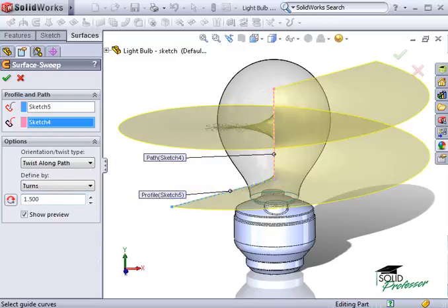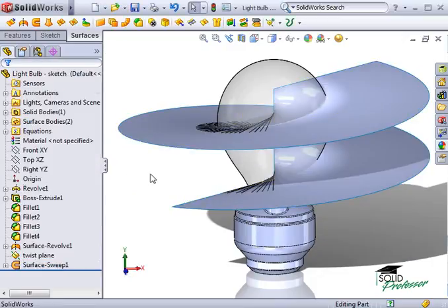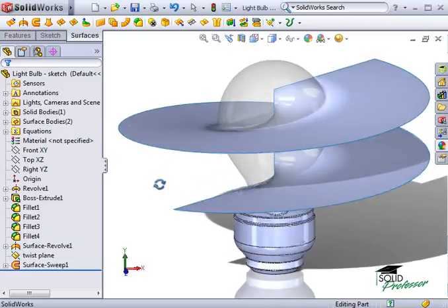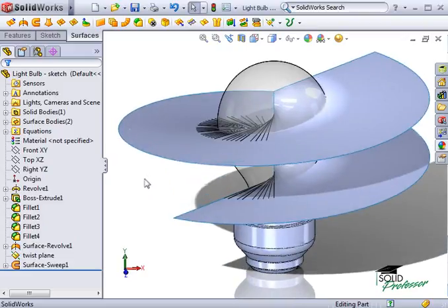Using this method is faster for creating a helical sweep than actually creating a helix. Since helixes, and in fact any curve features, cannot be copied or patterned, using this method gives me another advantage. Because the fluorescent tube needs two of these semi-helical sections, I need to create two curves separated by 180 degrees. To do this, I must copy the helical surface I just created.